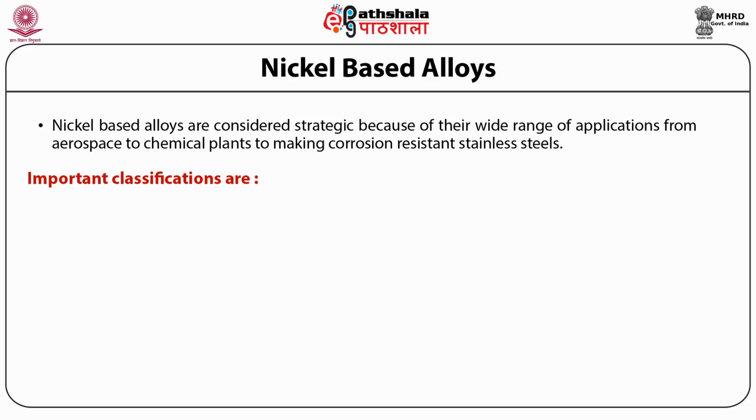Nickel and its alloys are classified into several groups. Commercially pure nickel has good mechanical properties and retains its strength at elevated temperature. It has also excellent resistance to most corrosive environments. It is used in making food processing equipment, electrical and electronic parts, caustic handling equipments, etc.